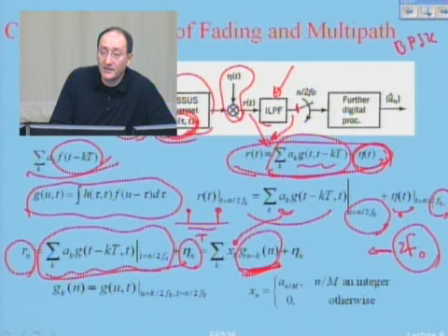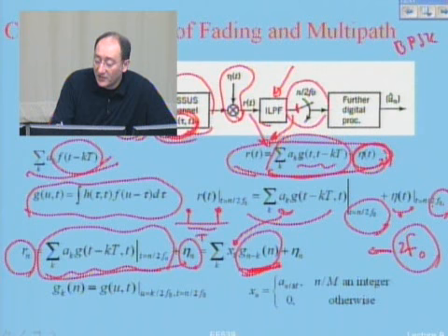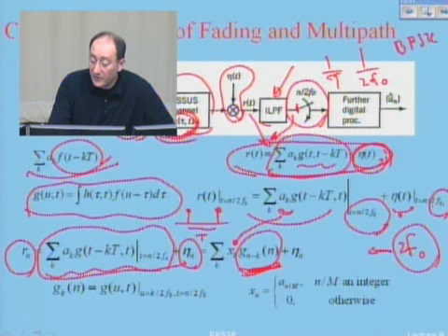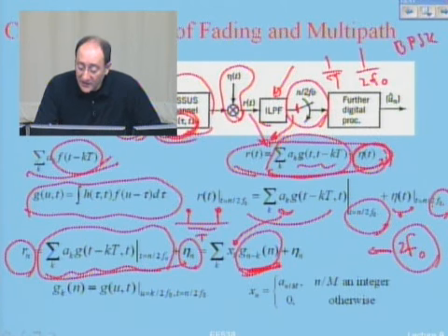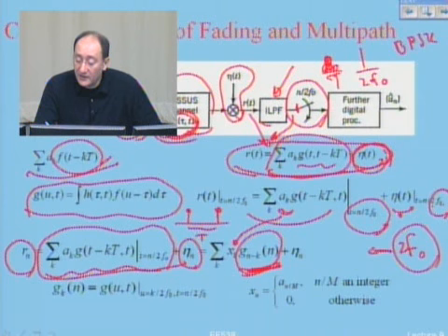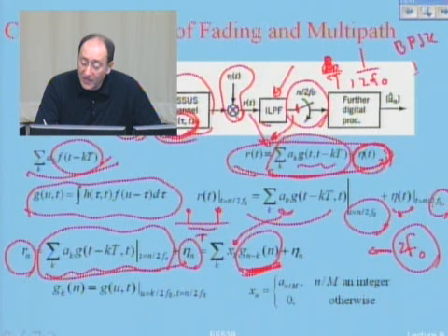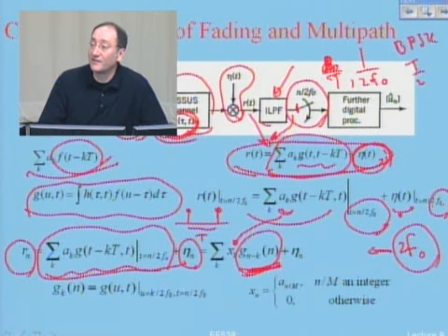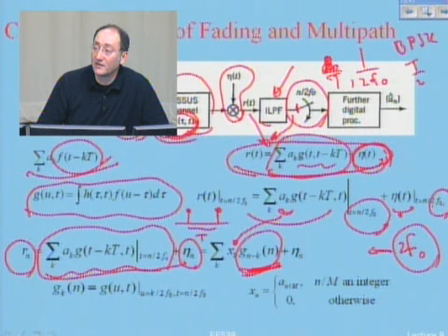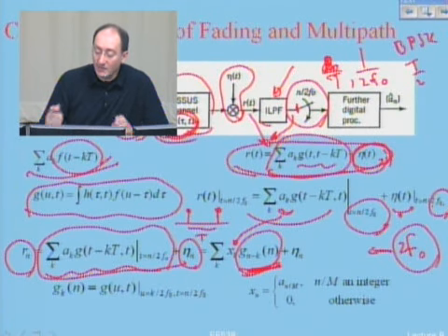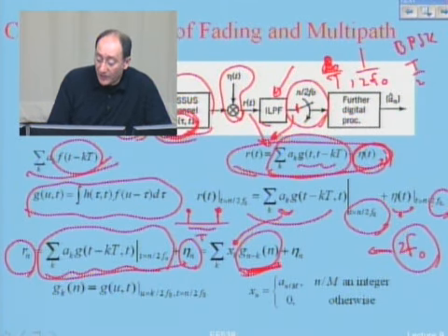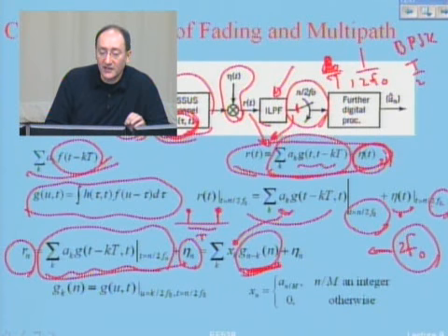Do you follow what I say? The sampling rate that I have in here is not at 1 over T. It is at 1 over 2 f naught, which is really 1/2 of T, T half, if you want to call it. Okay, so I'm sampling the signal for equivalent channel impulse response at a rate which is twice the transmission rate.